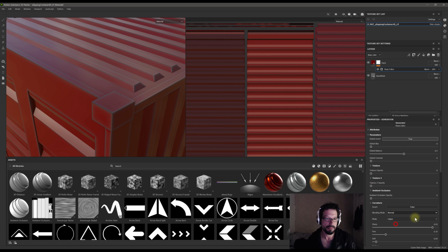But subtract, for example, is going to break this. Why? Because we are subtracting from nothing. If you subtract from nothing, you get nothing. There is no minus value in this mask. This mask, think in binary terms. It goes from 0, black, to 1.